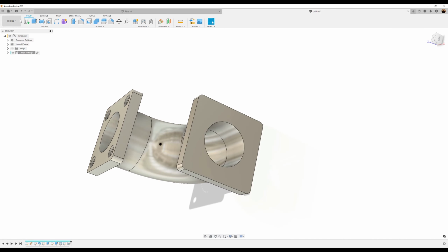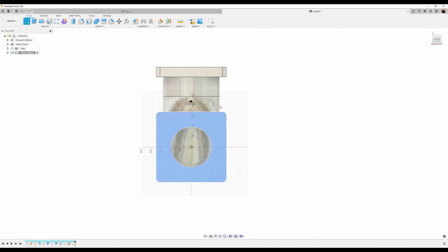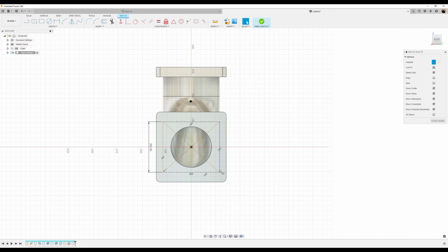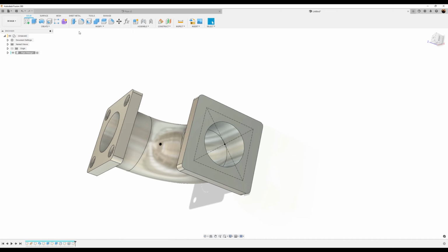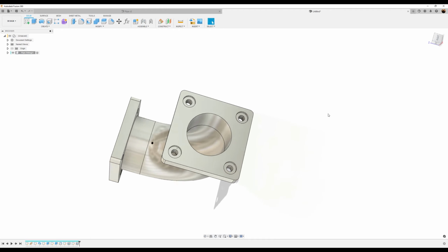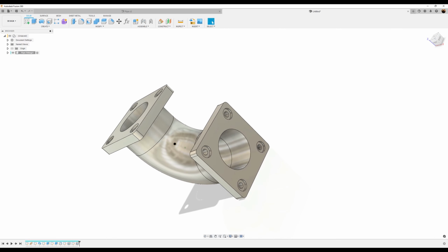All right. Now we're going to do the same thing for this actual edge right here. Center rectangle, construction only, 260 millimeters. Make all sides equal. Finish the sketch. Use the hole command. Select 4 points. Dimensions look correct. Parameters are also correct. Click OK. All right.